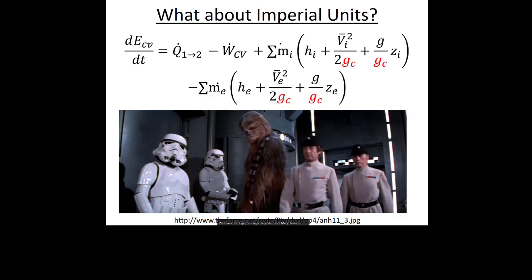It's also like an acceleration, so it's got feet per second squared. But then in the units, we have to change that pounds mass to pounds force. So its units are not just feet per second squared, but then also pounds mass per pound force. That's also on the equation sheet that I provide for the course.